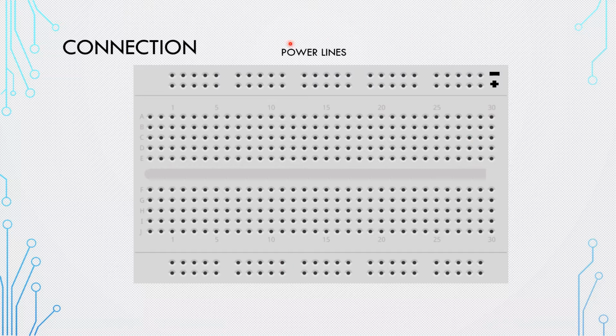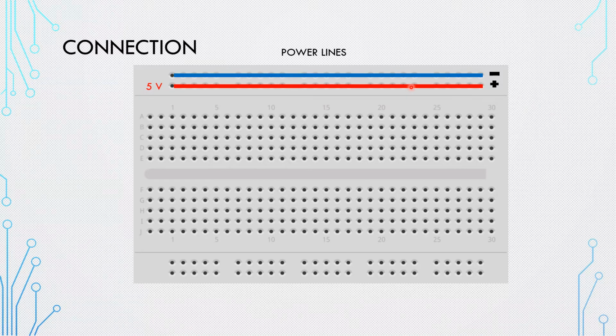So this is the breadboard. First of all, we have the power lines, where you're gonna supply 5-volt and the ground. You're gonna supply it from these 2 lines. We call this the power line. So this whole line we're gonna consider as 5-volt, and the negative line we consider as ground. Now if you bring the IC, this is how it looks like.